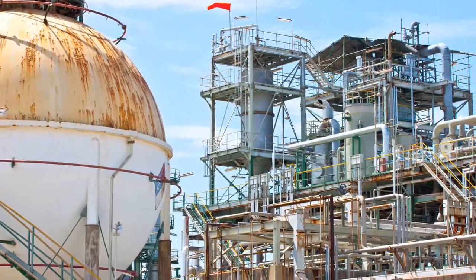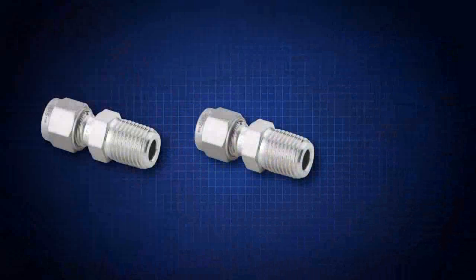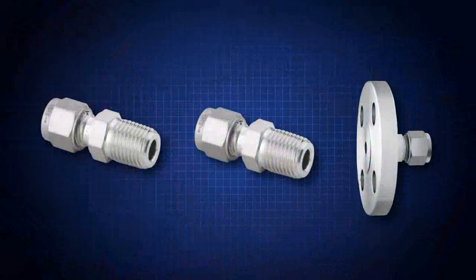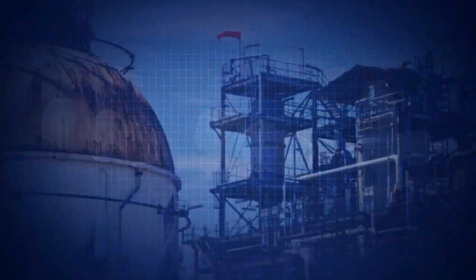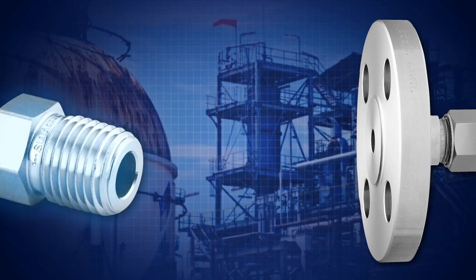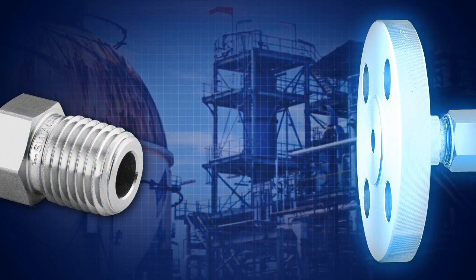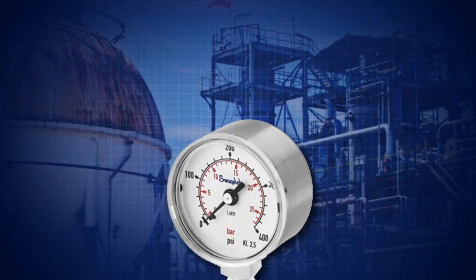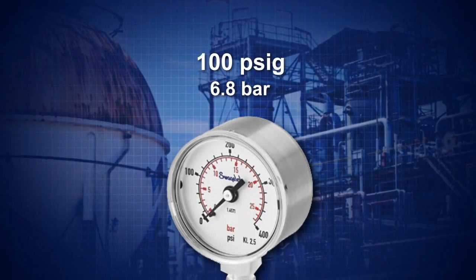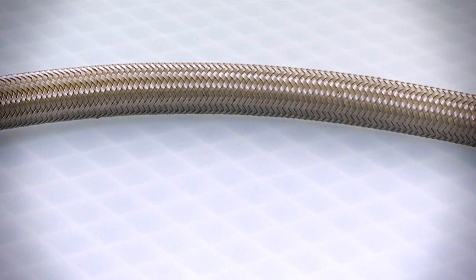In a general industry setting, NPT, ISO, BSP, and lap joint flanges are commonly used. Here's an example of a general industry setting that has a 1/2 inch threaded end connection on one end and a 1/2 inch lap joint flange on the other end. The system rating is 100 psig or 6.8 bar. The hose type selected is a fluoropolymer hose.